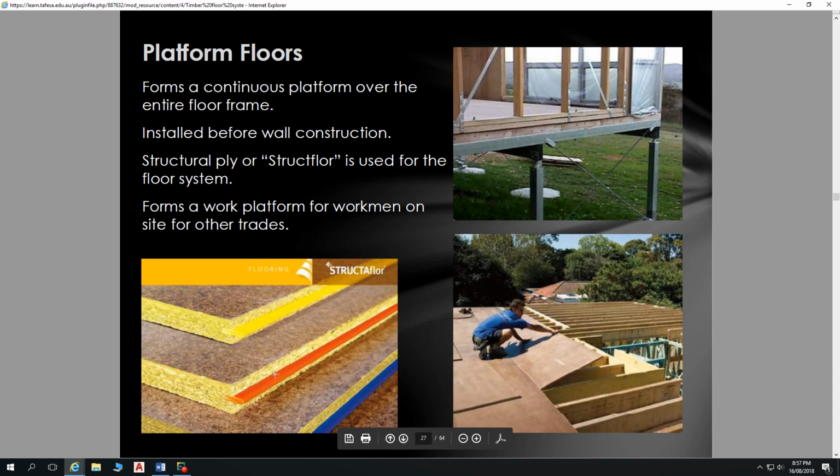We had one very expensive repair job come through where a designer had specified structural floor. Well, I don't know if the designer specified it or the builder just used it. Anyhow, the structural floor got used on a balcony, and those same sheets went under the external wall and came into the building. Of course, that structural floor didn't last very long exposed to the weather outside. The tiles over the top leaked, and when you get water on this, it doesn't last very long. It swells up very quickly.